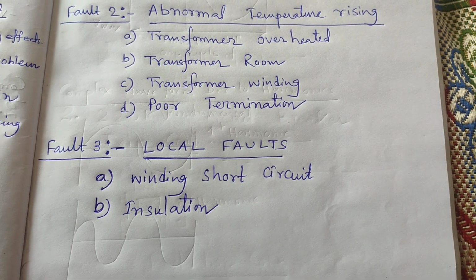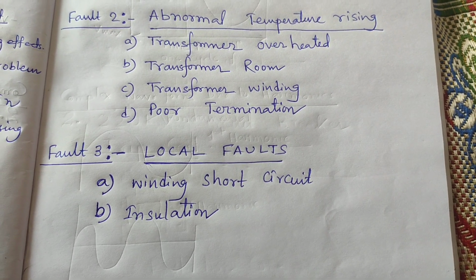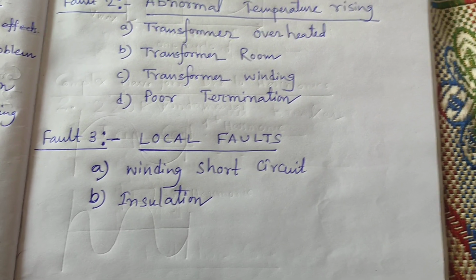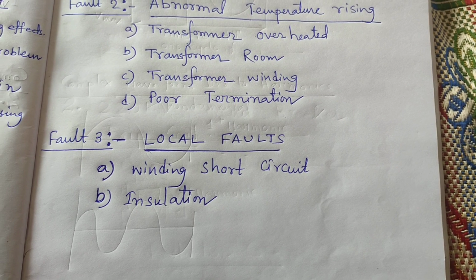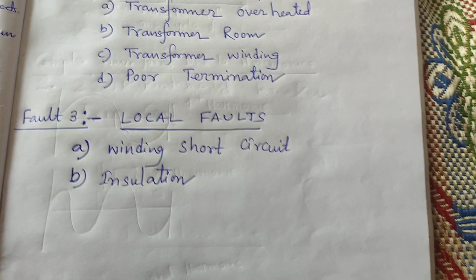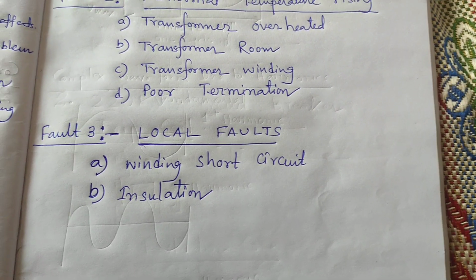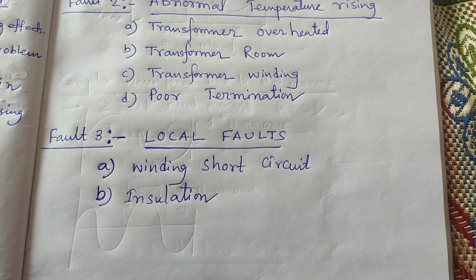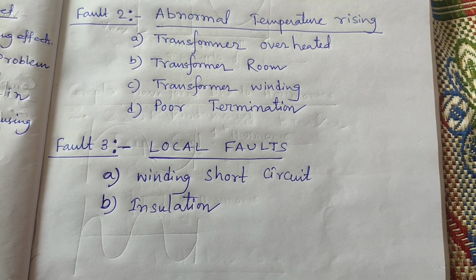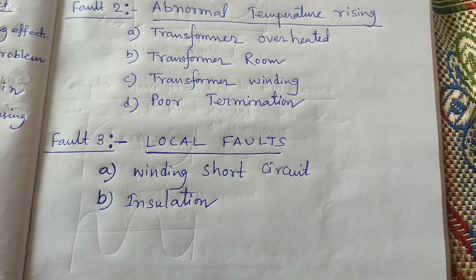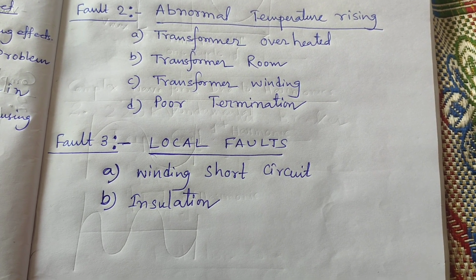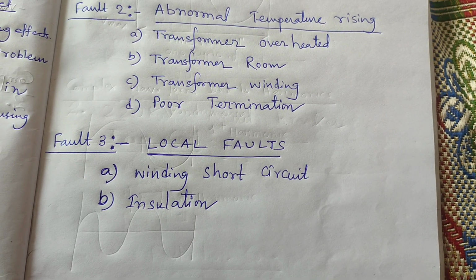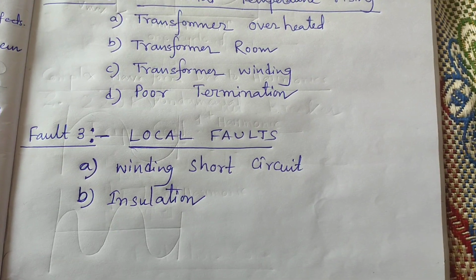This breathe in and breathe out process you can see inside the oil, so it should be checked and changed periodically. The oil level is minimum or maximum. If the oil level is below the minimum level, we should pour some oil inside the cup, and place it properly below the breather for the proper breathing process of the transformer.